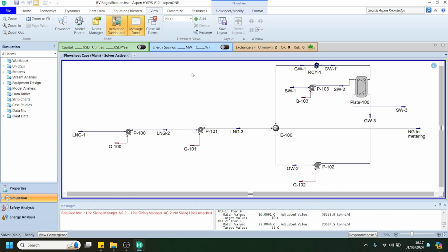Then finally we obtain the regasification system here, and actually this system is commonly found in floating storage and regasification units due to its compact design, making it preferable to be installed in limited areas. For the overall heating process, the LNG will be heated by Glycol-Water, and the Glycol-Water will be heated by seawater, and then seawater will be discharged at a temperature of 30 centigrade.